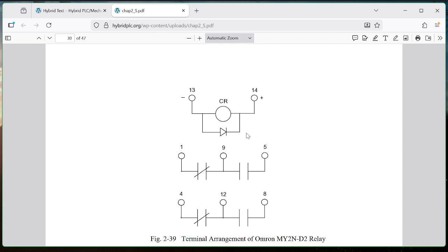It chews up the contacts on a motor starter, but here the current goes backwards through a flyback diode. It's built in, you don't have to put it on. It's built in to that relay, so that when you turn the relay off, the current that's still in that inductor has a place to go, and it goes right around and dies, it decays with an exponential decay, and it's gone. But it has a place to go. Everybody follow that? That's why that's in there.